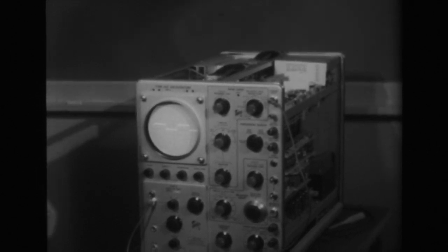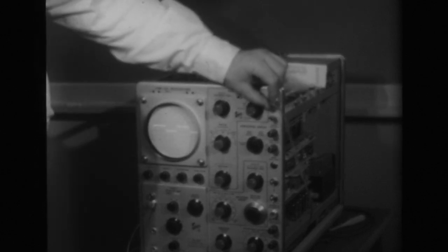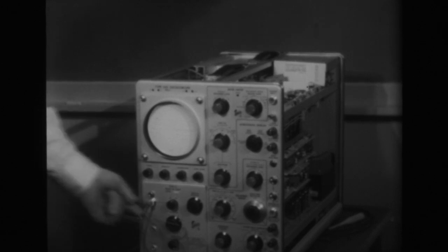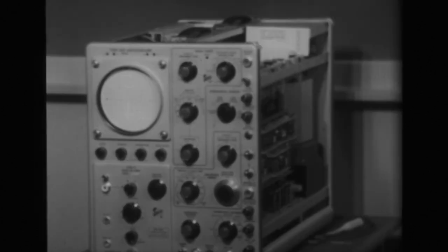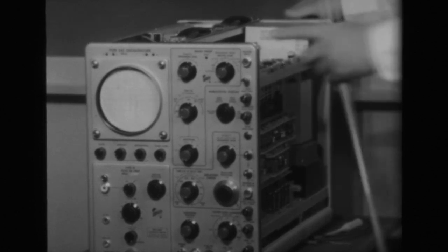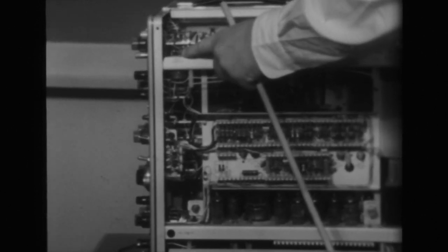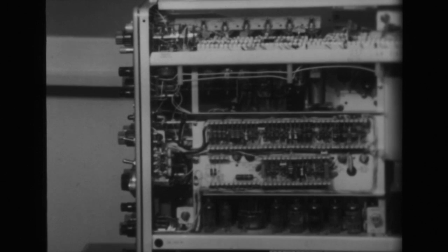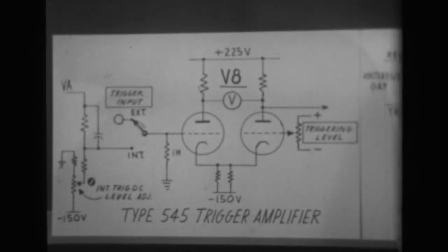And by setting a measurable hysteresis gap, we will be certain that aging of the tube will still leave the scope trigger system in a good usable condition. Now, for those of you having scopes with a preset stability control located in this corner of the scope, make the proper adjustment for the preset stability control according to the procedure outlined in your instruction manual.